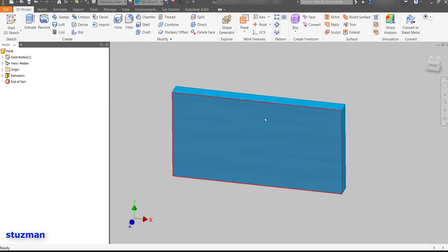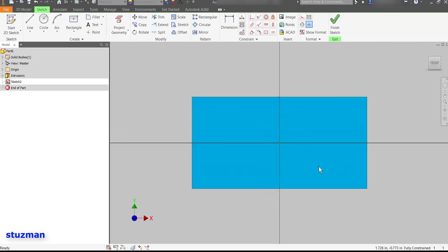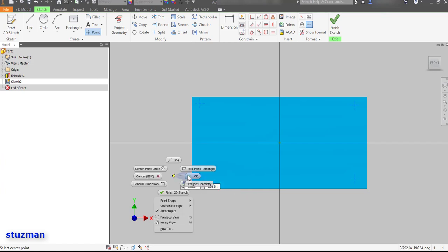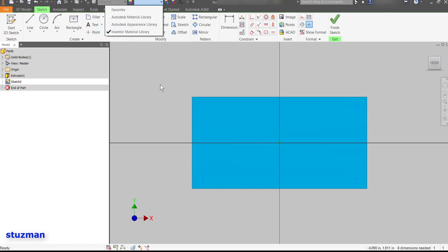All right, so now we need to put some holes in this thing. Say four holes in the corners, 1/4 inch off from each end. So I click on this face, come down to here, and create another sketch. Okay, so now let's go to this point, and I'm just going to click the points where I want these holes to be. In fact, it's pretty hard to see that, so let me just back up.